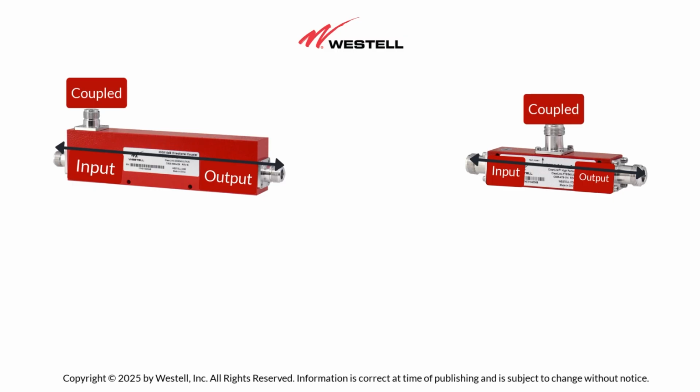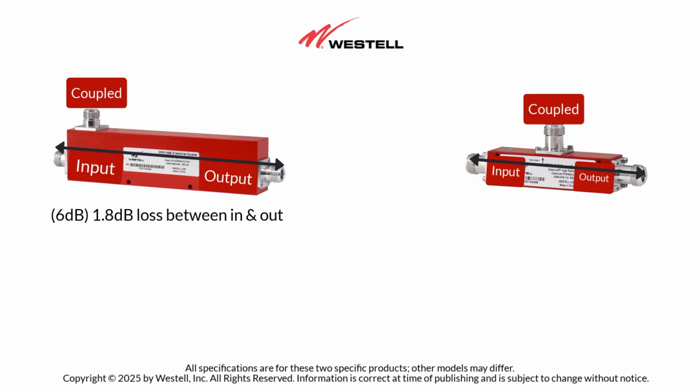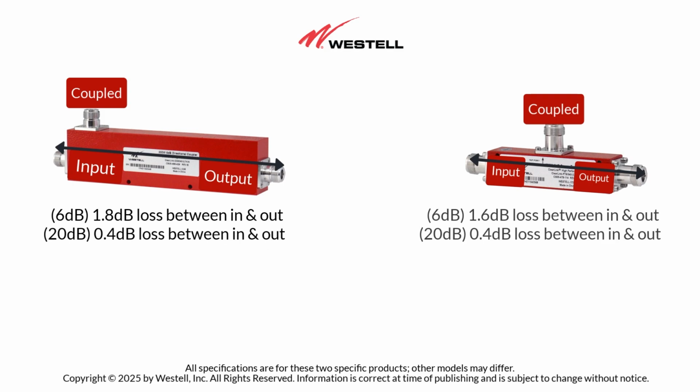There is no single answer to this, as the amount of attenuation at the coupled port impacts the signal loss between the input and output ports. For instance, a 6 dB directional coupler may experience around 1.8 dB of loss between the input and output ports, while a 20 dB model might only have 0.4 dB of loss. Tappers operate similarly, but generally exhibit slightly less loss compared to directional couplers.